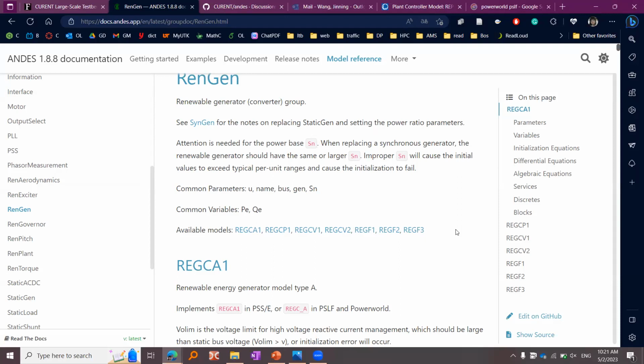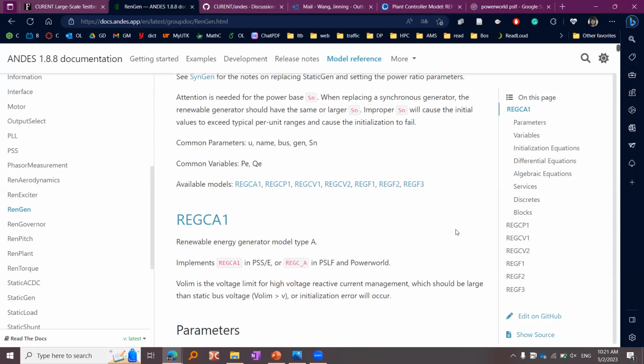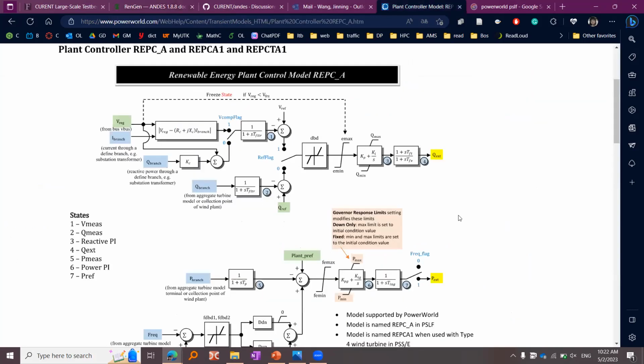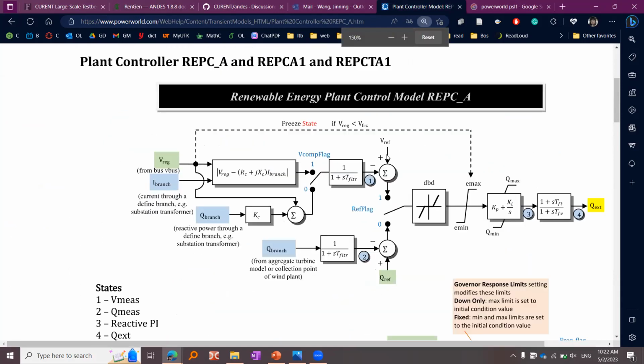For a traditional generator, I've got the exciter model with a hard limit due to the current limits, but there's actually quite a bit of room in there, so you don't go into those hard limits very easily. Like in what Jinning just pulled up, you saw several blocks that had limits on them. Those limits are a lot tighter for power electronics. You look at these, say Qmax and Pmax, and they are going to be tighter, and that's going to make a difference in your simulations.